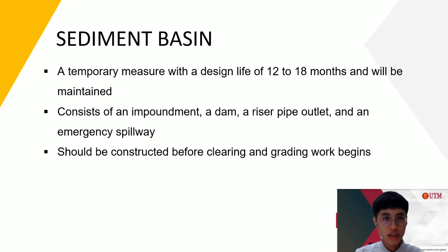Sediment basins are suitable for nearly all types of construction projects. It is a temporary measure with a design life of 12 to 18 months and will be maintained until the site area is permanently protected against erosion. A sediment basin usually consists of an impoundment, a dam, a riser pipe outlet, and an emergency spillway. This should be constructed before the clearing and grading work begins.